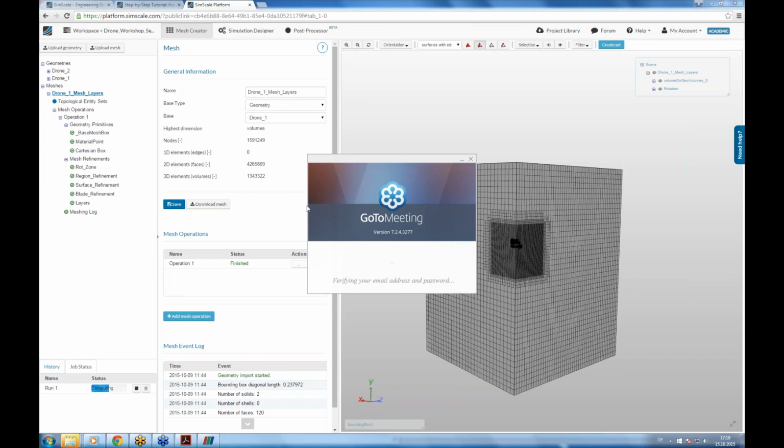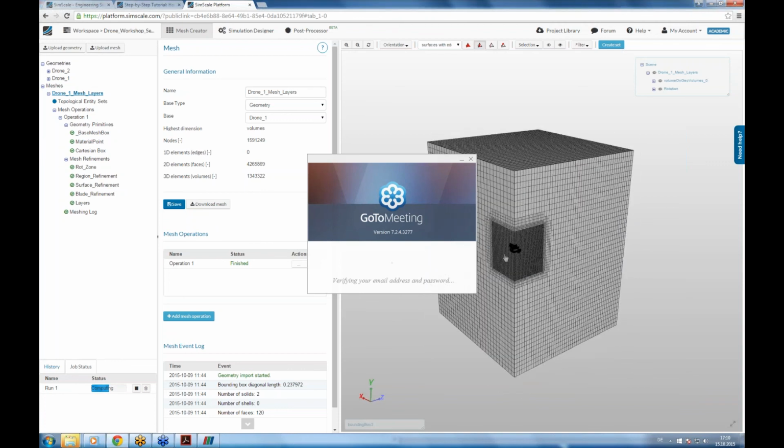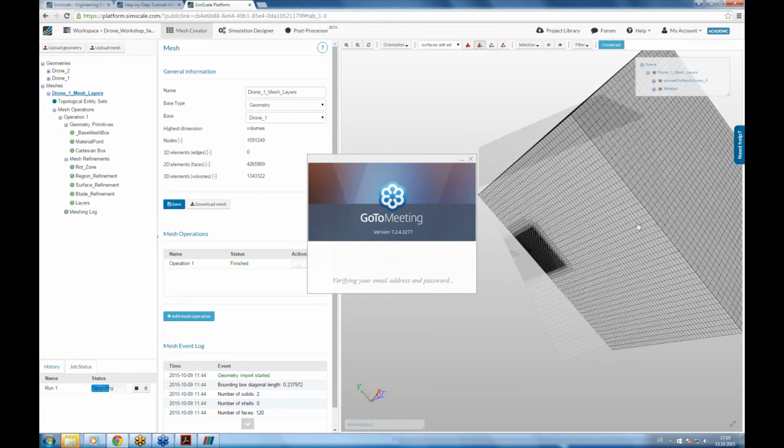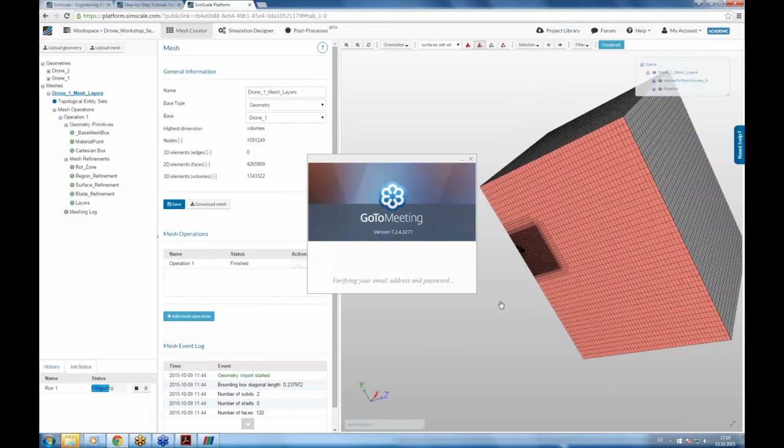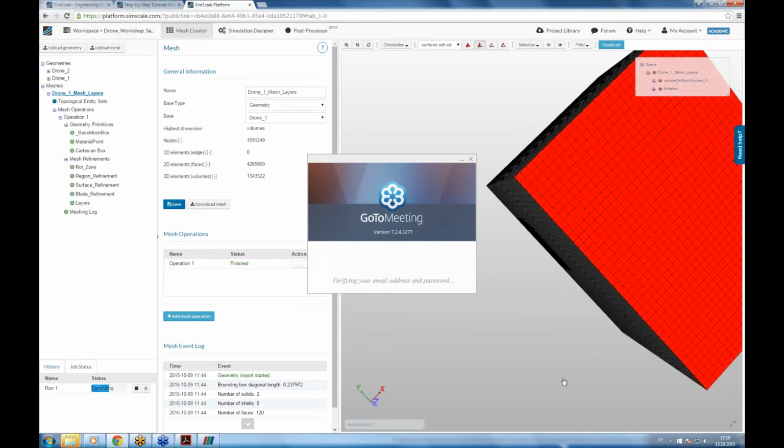In this case, we know that because the box is so big, the influence will not be so negative on the result, and it's easier to set it up this way, with the air circulating here. That was, by the way, the reason why we use this slip wall boundary condition for this wall and for the outer walls, to minimize this effect. But you're right, it's also possible to have air which would leave and come into the box, and that is exactly what you will do in homework number 2.